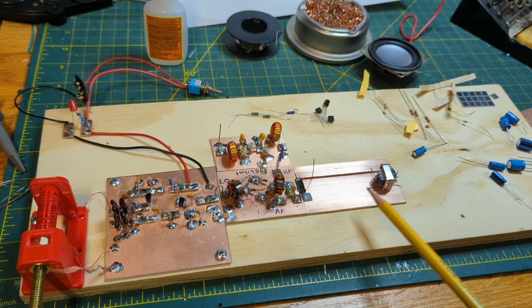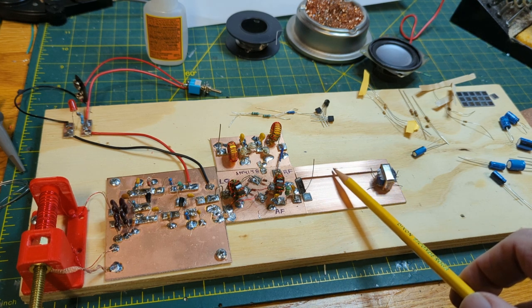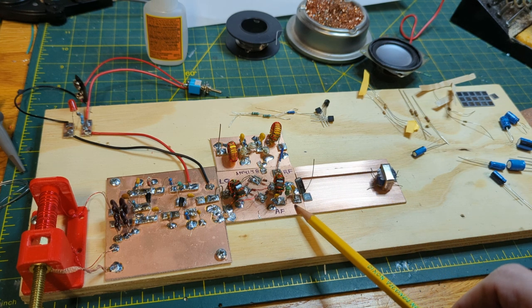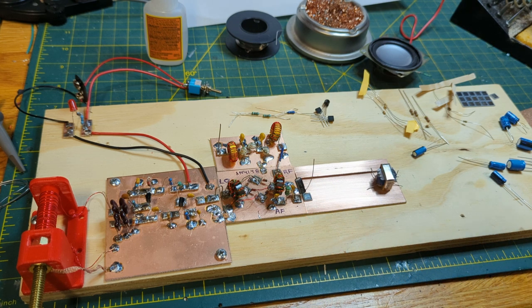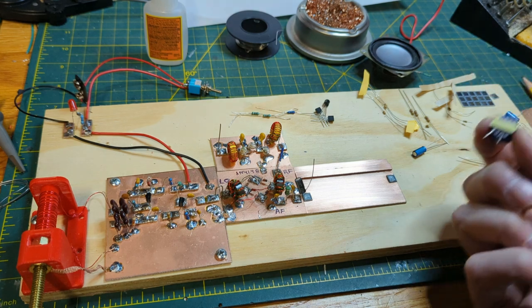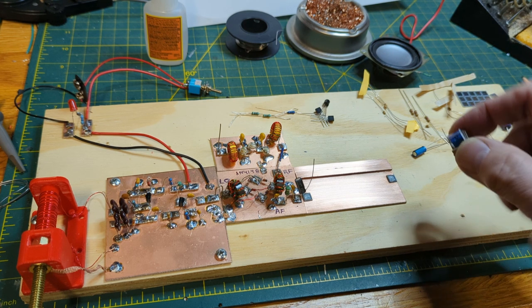I started by doing a little bit of layout planning for the board. So I have the power rail here. I have the input pad here, which is going to go to the mixer. It's going to go right to the cap that's coming out of the mixer. And then I kind of laid out where I want the audio transformer to go. I bent the leads so that one of them is going to go to the power rail.